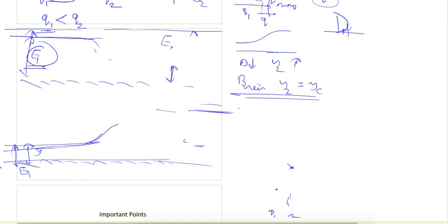And if I want to reduce B less than B minimum, then there will be a new specific energy at section 1, let's call that E1 dash, and corresponding to that there will be a new specific energy at section 2 also, which is E2 dash, and as we saw the specific energy remains the same. Corresponding to this new specific energy there will be a critical depth at section 2, which will be YC dash, and this YC dash will be greater than the older YC.